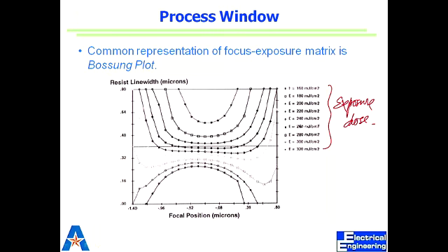Now I increase my energy. I can make a bigger line, and my depth of focus is also increasing. Now I can go from here to here, slightly larger than that. So if you put a line here and say, okay, this is acceptable intensity, then I can make that line. Does that make sense? You have to feel it in 3 dimensions. So I'm changing my intensity, energy, and my depth of focus is changing, right? The range which is valid is changing, because if I go too far away from that plane, my line width is becoming 0. Essentially, I'm not getting any exposure. In this case as well, if I'm getting too far away from my plane of focus, my line is becoming too wide.